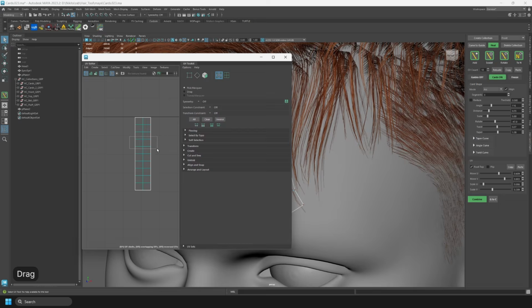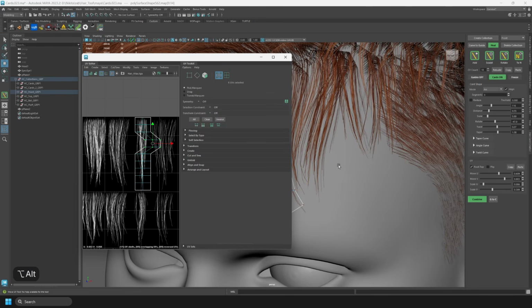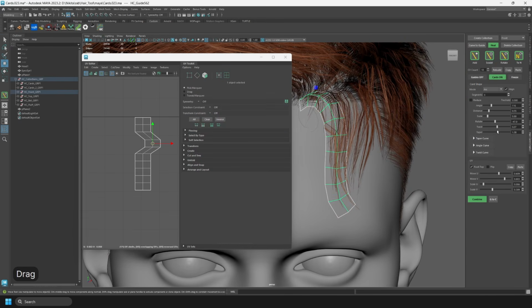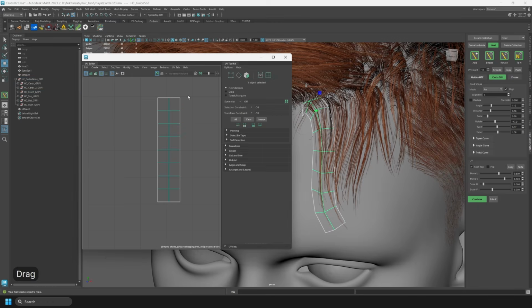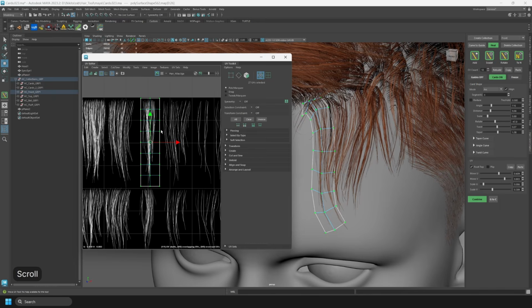Next is the UV module. It is better to edit UVs through the plugin tools rather than manually in the standard UV editor. The reason is that the card remains procedural. If you edit the UVs manually and then change segments, distance, or other card shape parameters, the manual edits may behave unpredictably. If the UVs were accidentally damaged, Heal can help restore the working state. For normal UV work, it is better to use the built-in manipulators. To see the texture, you usually need to select a card and go to UV.